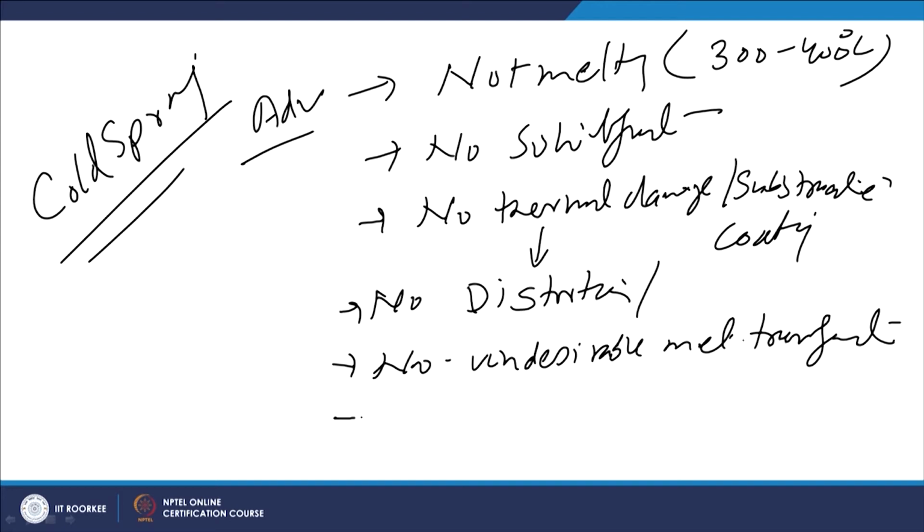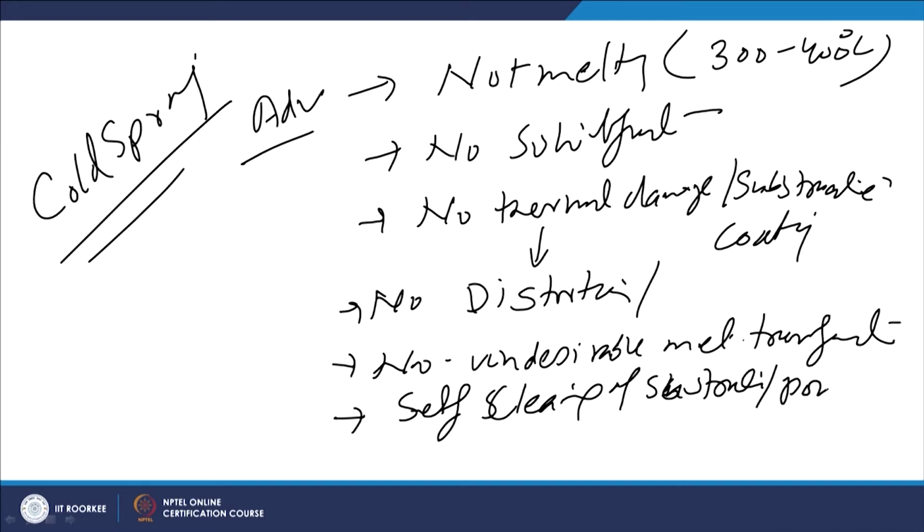At the same time, it also offers the advantage of the self cleaning of the substrate as well as powder particles due to the kind of plastic strain which is associated with the impact of the high kinetic energy powder particles at the surface of the substrate.